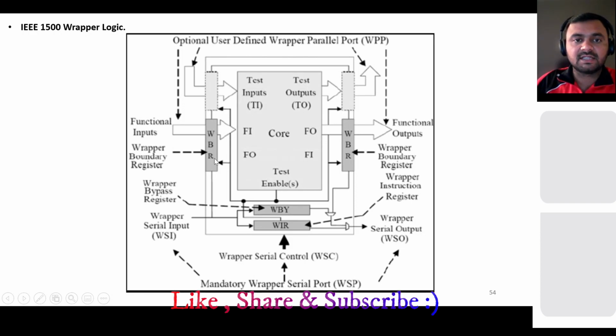So you just put the serial input here, and this will be connected again back to the top level TDI. Then you have a bypass register, then again the wrapper boundary register. As you have this IEEE boundary scan register, you have a wrapper boundary register, and then you have a functional input, and then functional output, and there are some serial output registers as well.